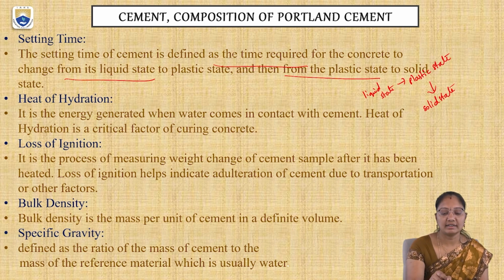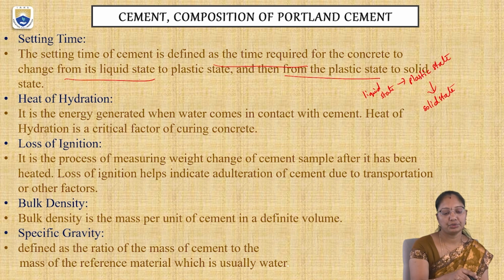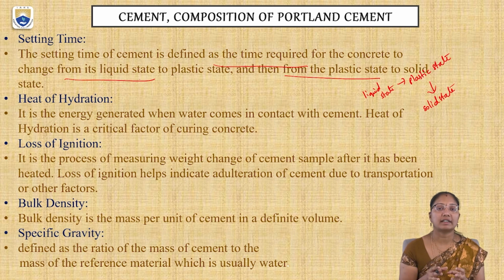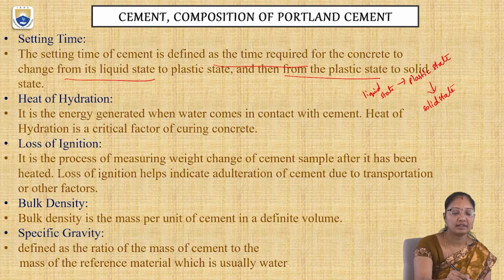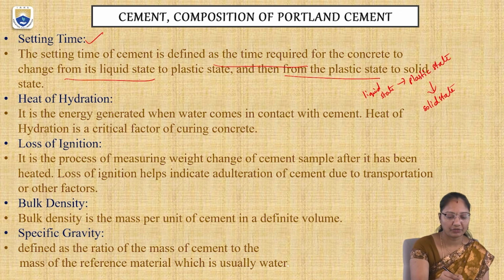So here it is defined as the setting time: the time required for the concrete to change from its liquid to plastic and plastic to solid state. The time required for this process is called the setting time. And next property is the heat of hydration.